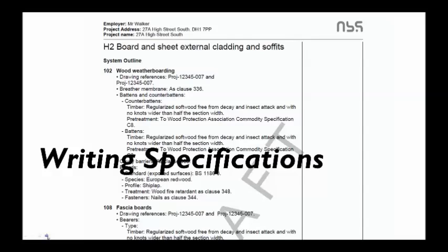And so you kind of go back and forth, and you can mix different sections, different materials in building systems. You can mix either prescriptive or proprietary specifications depending on what it is. So it's not like you have to pick all the manufacturers on all materials if you decide that's the way to go. Maybe it's just that you care more about some things than others, or on some things it doesn't matter.